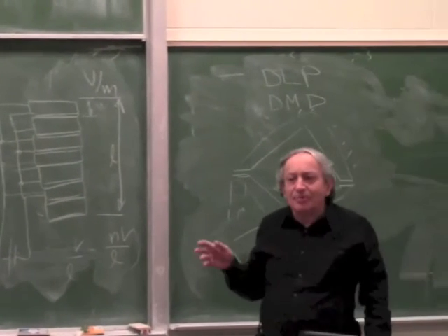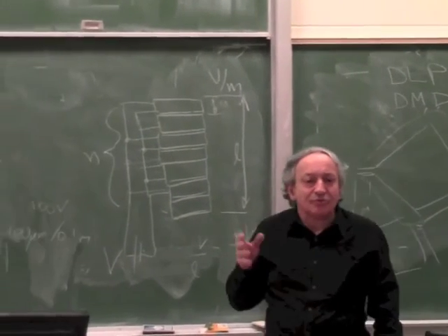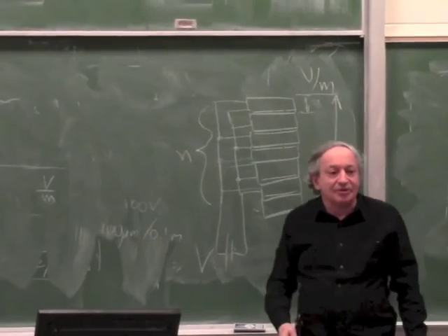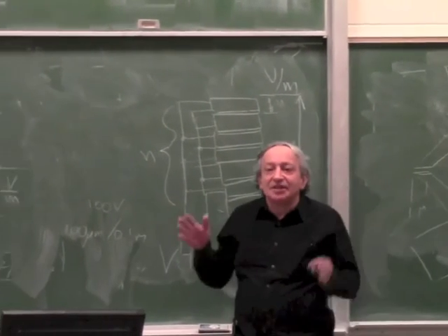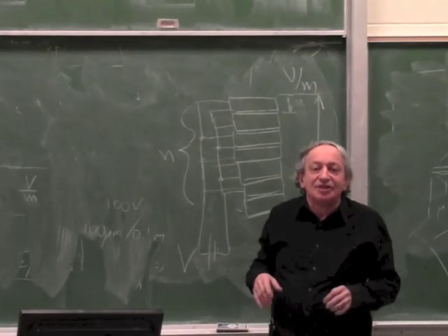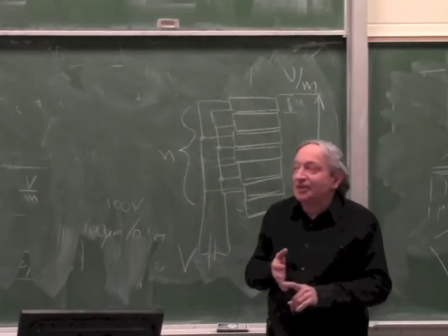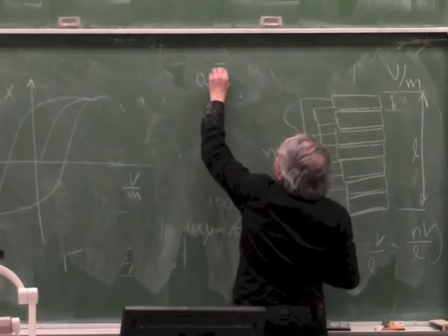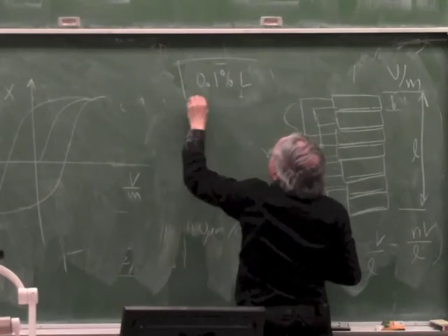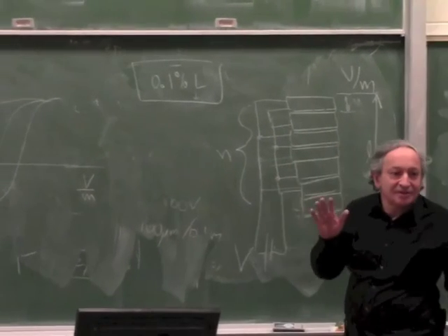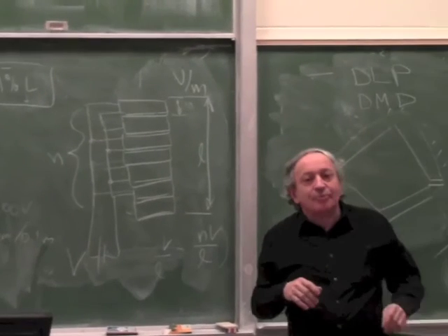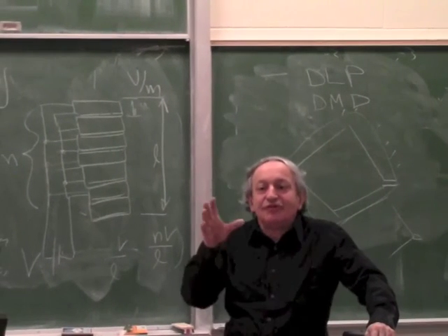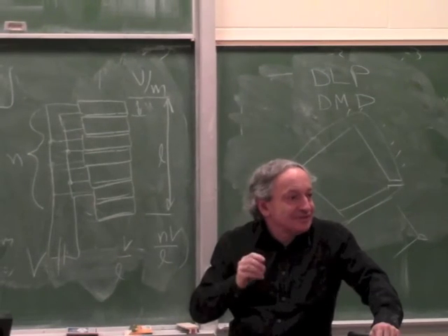Okay? It's comparable to magnetostriction. If you take a good magnetostrictive material, it's comparable. It's also 100 micron. Another way of saying it: the maximum movement of all these magnetostrictive actuators and piezo actuators is about 0.1% of the length. And that's it. Compared, say, to an electromagnetic actuator, which can move 50% of its length. So the movements are very small.